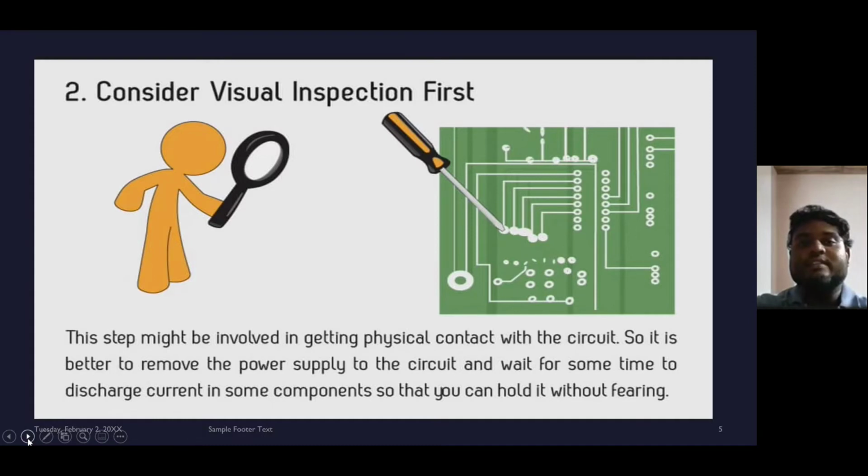And here we need to understand that if one of the conditions I mentioned requires immediate repair, then go for the repair action, like desoldering the shorted points, soldering the loose parts or connections, and replacing the burnt components with new ones.